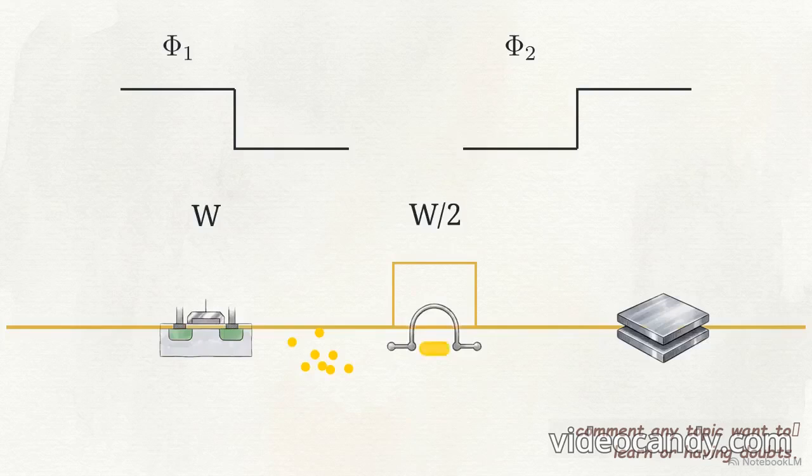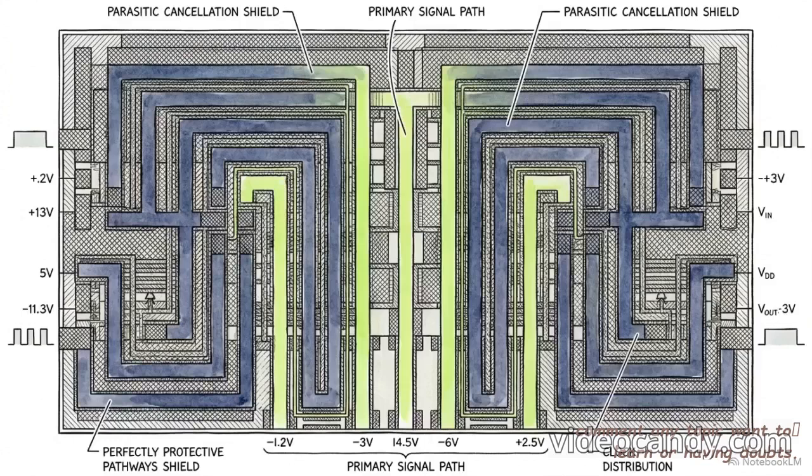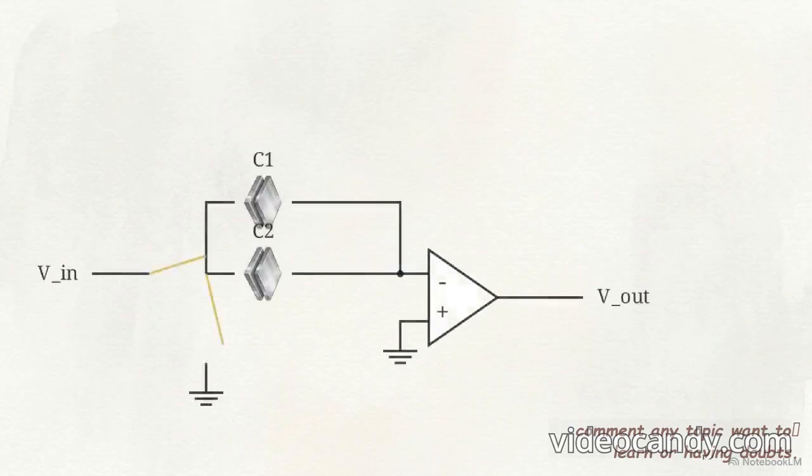As the main clock drops and the primary transistor turns off, expelling its error charge, the inverted clock goes high, turning the dummy switch on. By turning on at that exact moment, the dummy transistor creates its own channel. Because it is half the size of the main device, it acts as a vacuum, absorbing the exact quantity of error charge expelled in that direction before those stray electrons can ever reach the sampling capacitor.